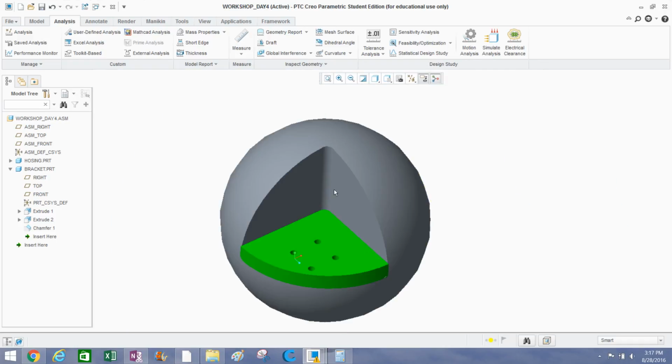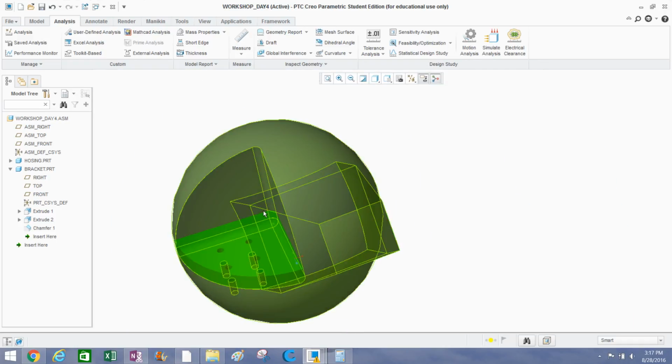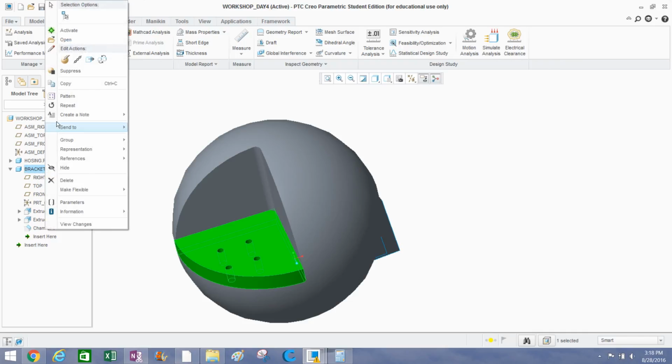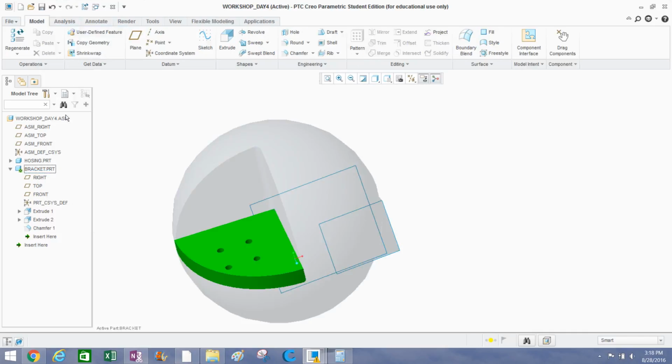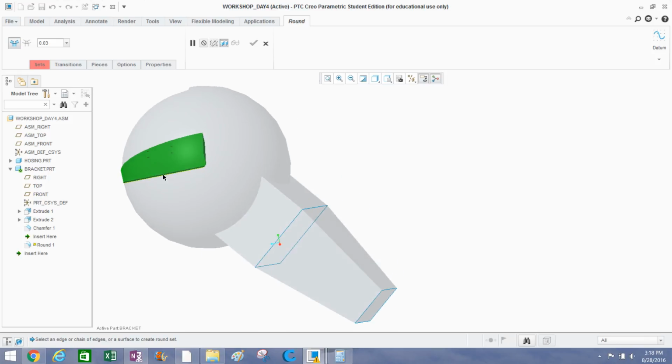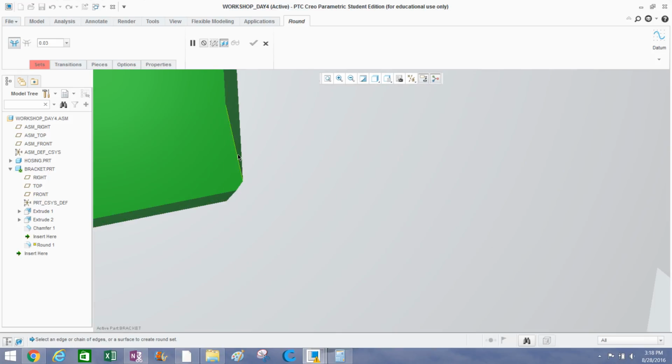And obviously you could try this stuff on your own and kind of use this video to check your results. So we go to the bracket, we'll go ahead and activate the bracket. And you don't even actually have a feature for it, so let's go ahead and create the feature. So like we did before, let's get the round. And we're going to try for that back corner back here.